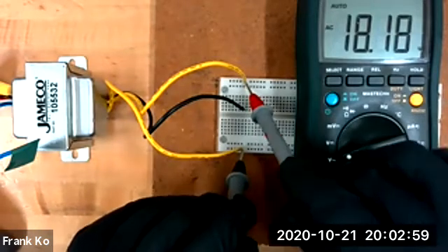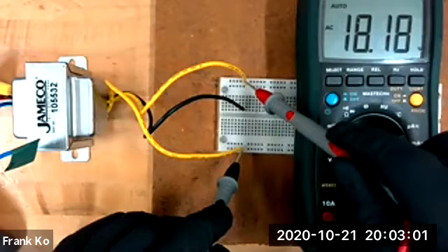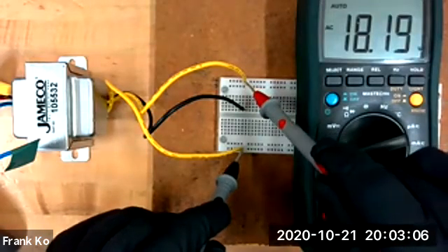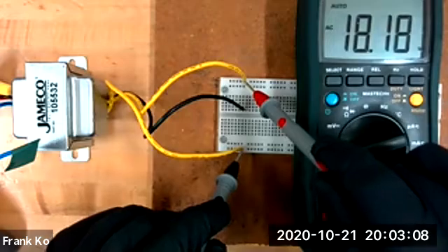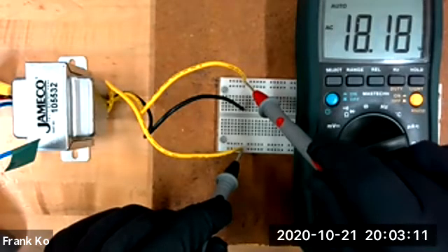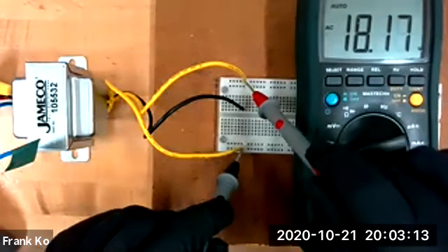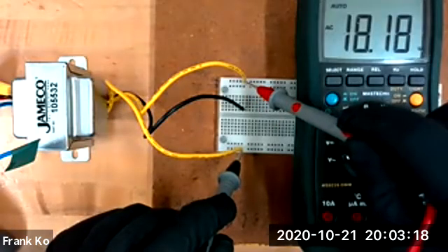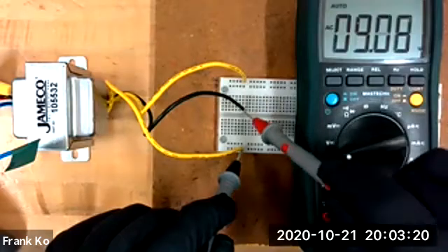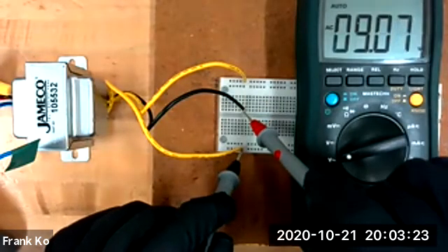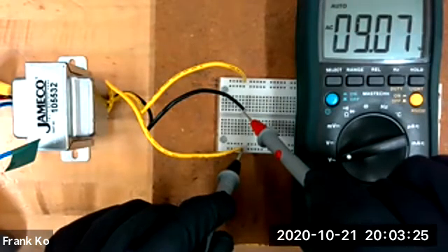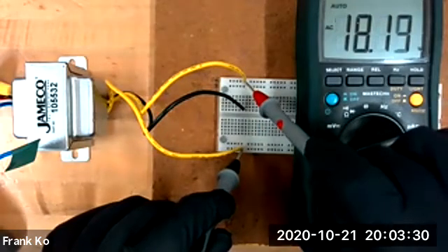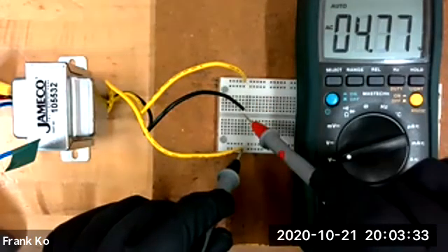Anyway, so if you go to measure between the two secondary wires, a little bit of metal that's sticking up, I'm measuring 18.19 volts, and then if I watch this, watch me, watch the screen. So measuring my two outside wires, my secondary wires, I get 18.19, and if I measure between that and the secondary, the center tap, is my center tap half of the secondary? Because this was 18 and change, 18.19, and then 9.12.